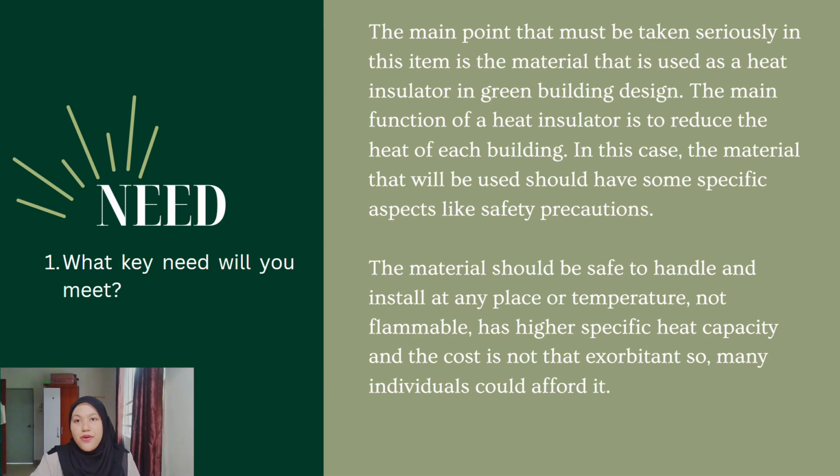The main point that must be taken seriously in this item is the material that is used as heat insulator in greenhouse building. The main function of heat insulation is to reduce the heat of each building. In this case, the material to be used should have some specific aspects, such as safety precautions. The material should be safe to handle and install at any place or temperature, not flammable, have a higher specific heat capacity, and the cost should not be exorbitant, so many individuals can afford it.